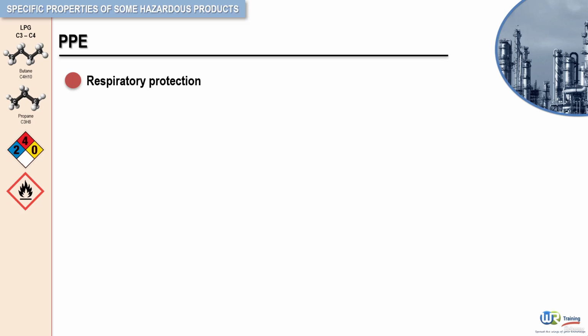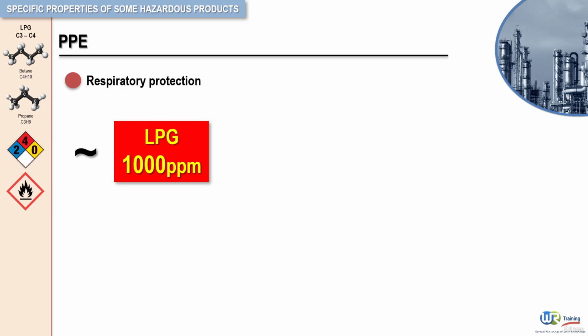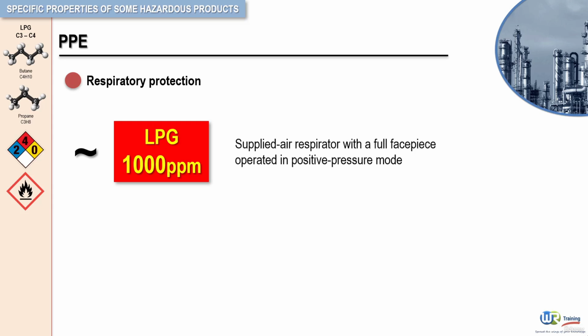Now, when the potential exists for liquefied petroleum gas exposure over 1000 ppm, use an approved supplied air respirator with a full face piece operated in positive pressure mode. And for increased protection, use in combination with an auxiliary self-contained breathing apparatus or an emergency escape air cylinder.